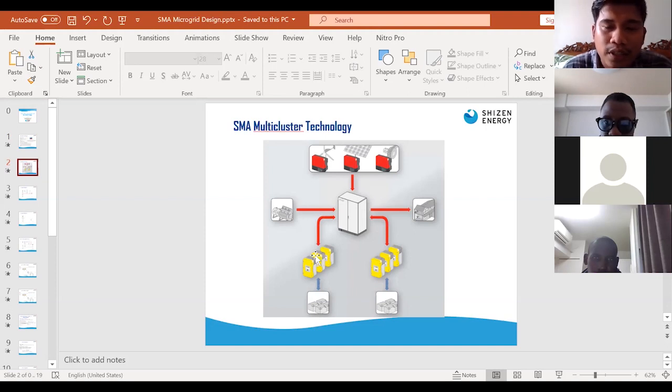During the day, when the sun is up and producing power, this battery inverter will form the grid. They produce the grid as a reference, because you know that a solar inverter is on-grid. They will operate when they read any grid reference, right? Because we are not connected to the main grid, the battery inverter will function as a grid during the day.